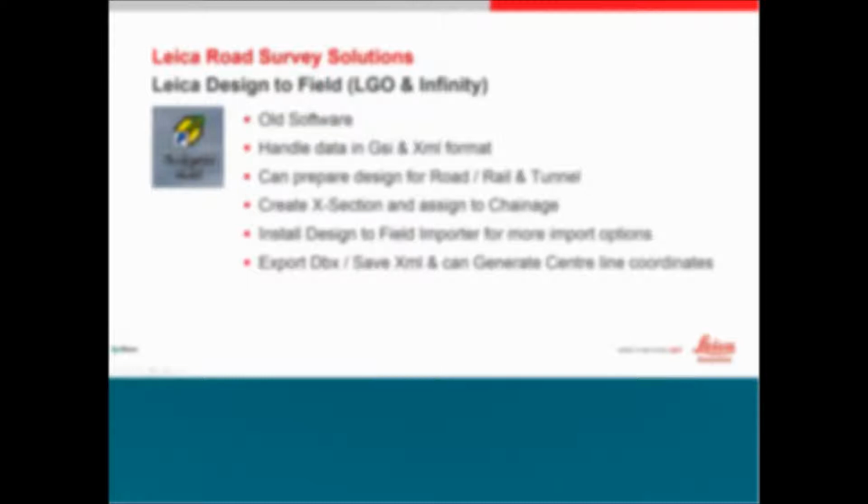It's an older software. It handles GSI format, or it takes in XML format and exports XML format. It can also export to the SmartWorx Viva format. Like I say, you can prepare road, rail, or tunnel data, create cross sections, and assign cross section changes.